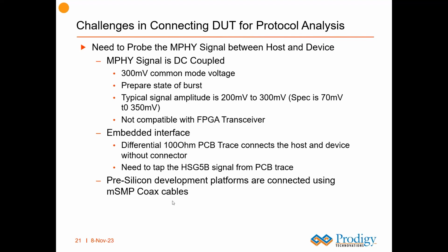But when you are developing a device or a SoC, you do a lot of FPGA-based prototyping. That's in the pre-silicon environment, so it is very challenging to see how to probe that. If you want to look at the traffic between the host and device when you run a test case, what's exactly being transferred, using a protocol analyzer, it's very complicated to probe that. So how we solve this problem, we will see in the next slide.